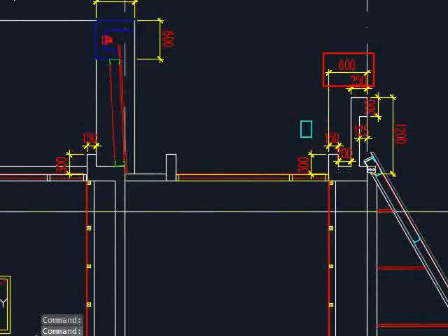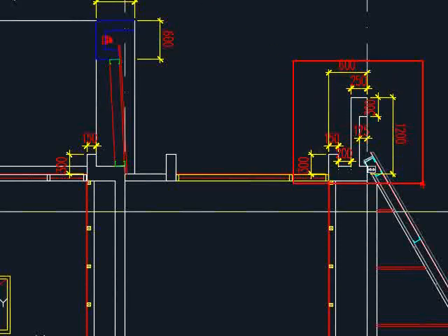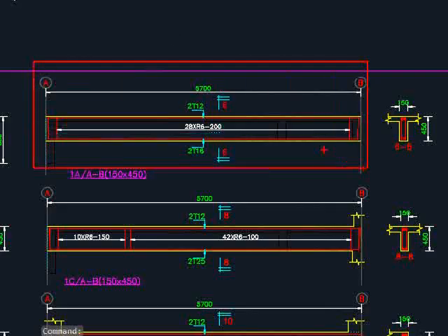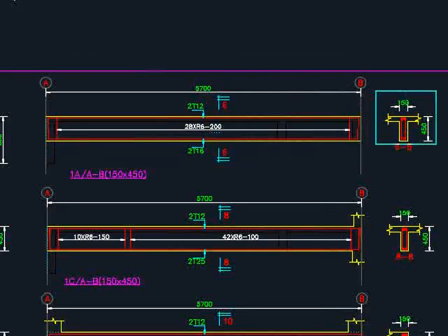Clearly indicate every single dimension as per the architectural drawing, as well as the reinforcement bar inside the members. Let's say now if you are producing the detailings for this beam, you should have a member something like this, and then the cross sections with the reinforcement bar should be in accordance with the shapes as given in the cross sections of the structures by the architect.